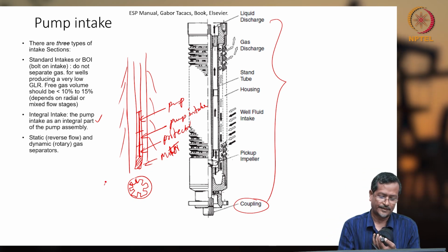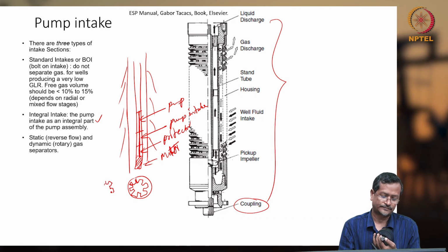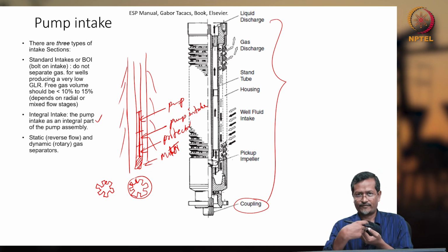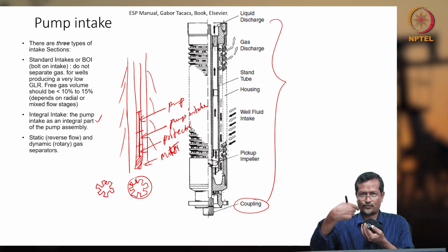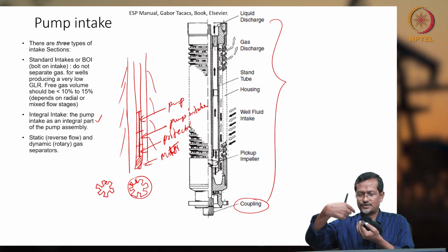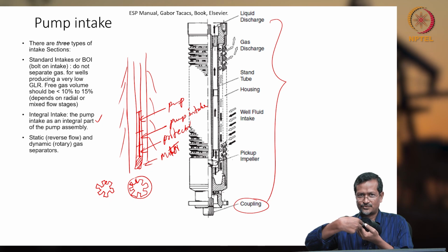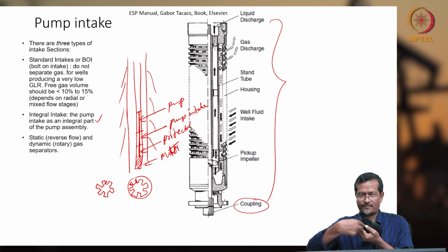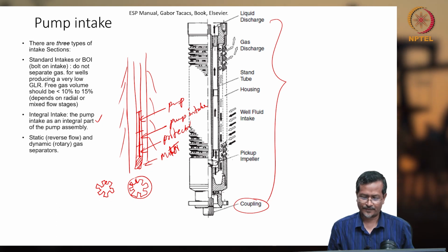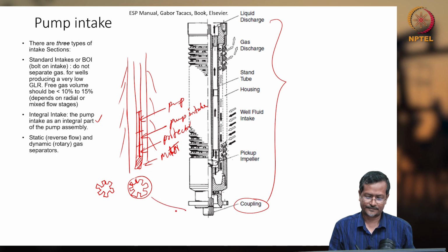The shaft end will have this cavity, and the outside of the other shaft will be like gear teeth sort of thing. So you just put it here. It will give enough axial alignment space and some radial flexibility also. So this sort of connection will be there. This is the coupling.